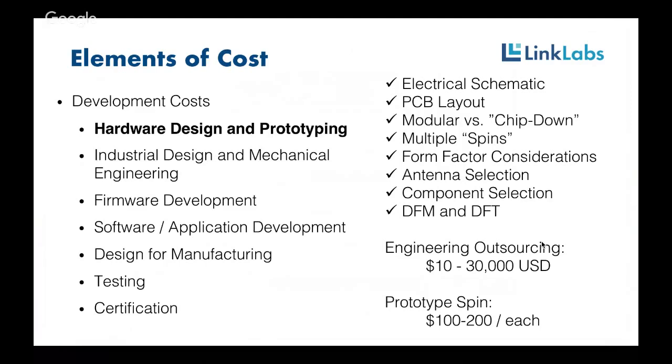Generally, those modules cost anywhere from 2 to 5x what the chips inside of them cost, because you have to pay for those vendors to supply that solution. Going chip down always is going to result in a lower BOM cost, but your cost of development, certification, testing is always going to be higher because you have to pay for that development.